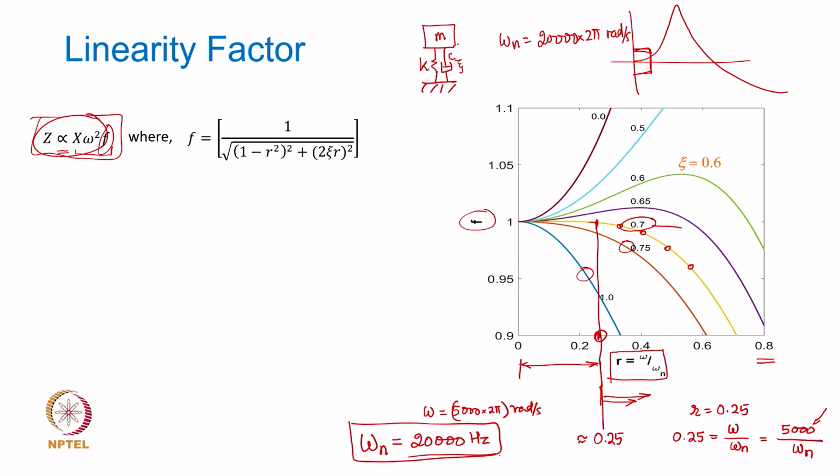So, you need to pick up appropriate piezoelectric material and then ensure that the drop in this f value is not beyond a certain range. Okay, that is how most of the sensors are designed, and therefore, in contrast to the seismometer, which is expected to have a very low natural frequency, the accelerometer is on the other side of it, that it is expected to have a very high natural frequency.